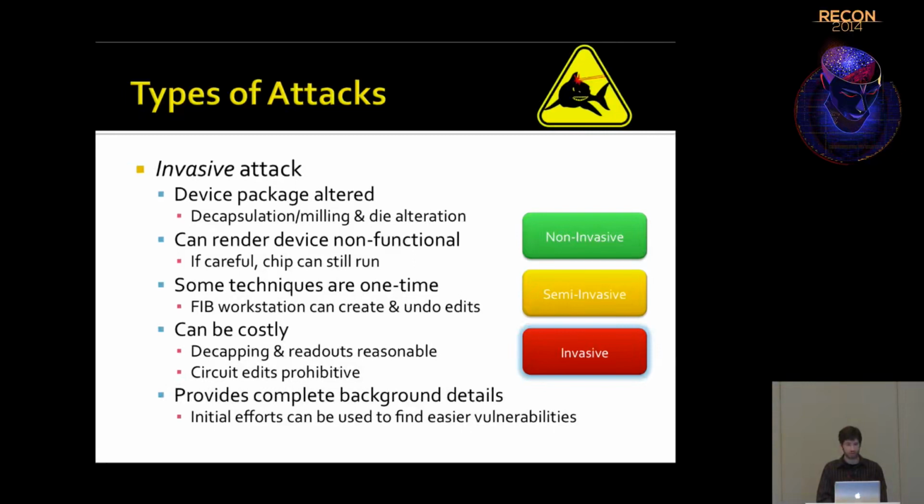So you're basically doing the nanometer equivalent of plasma cutting and welding, where you're depositing material and you're removing material, i.e. cutting traces or power traces or signal traces, or adding vias or test points that were not there before that give you access to a trace deep inside the chip. So this class of attack can certainly render the device non-functional, especially if you're imaging the chip layer by layer.